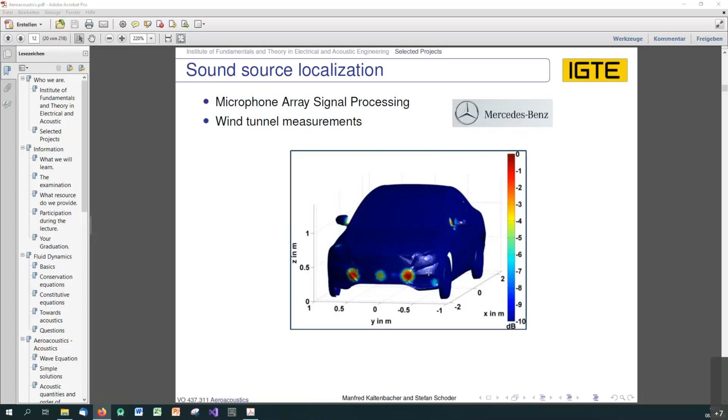Yeah, the fancy stuff there was that we used the free field Green's function of the wave radiation, and therefore we somehow disconnected the flow from the acoustics. Okay, and you do it afterwards via post-processing of the signals. Yeah, that's purely signal processing. Okay. That's very specific for that. But as you pointed out, it is a big challenge to measure when you have flow.